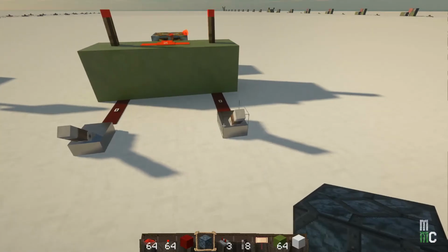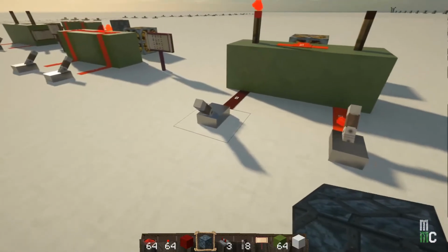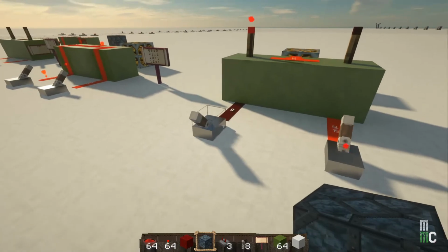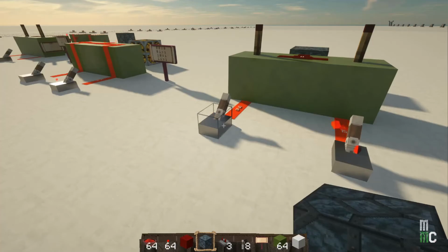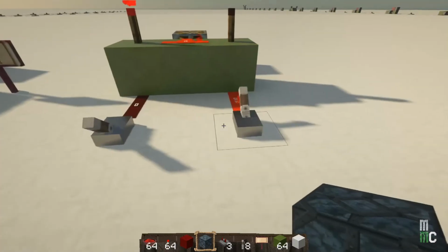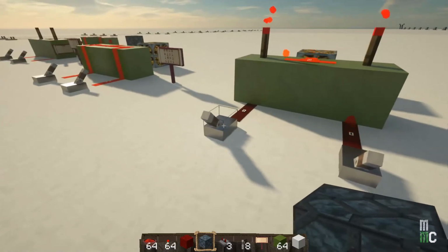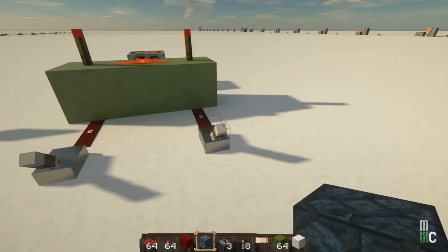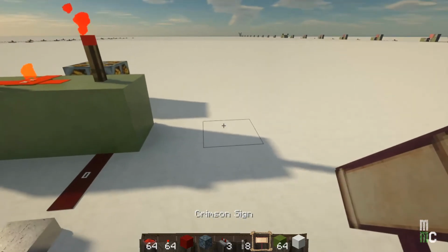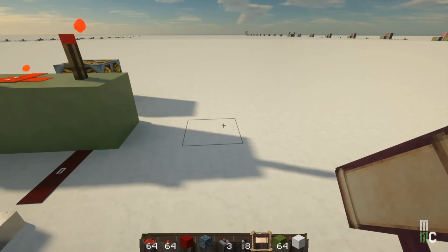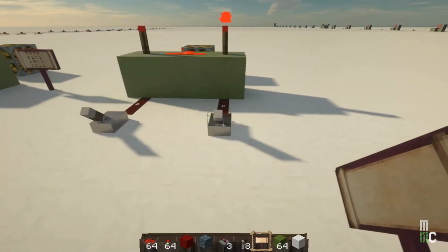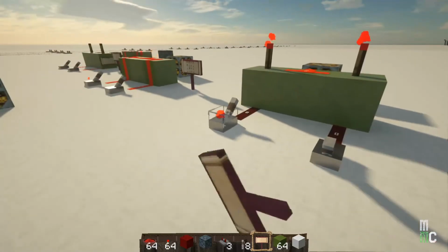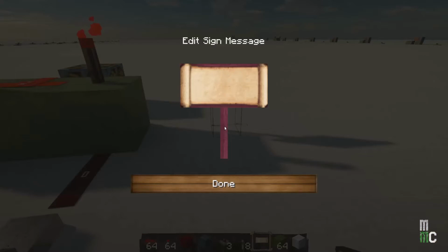Now you can see it's on with both of these on. Let's flip these around. Okay, when they're both on, the gate is off. If any switch is on, it's on, and if they're both off, it's on. So the output of the NAND gate is negated AND. So as you can see, any combination but this one, the light comes on.